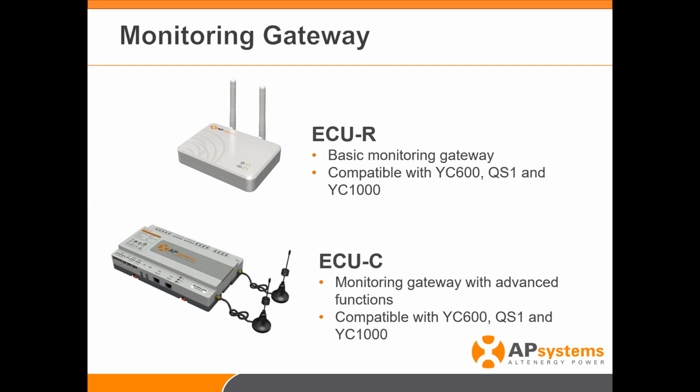It says, what type of commands can I send to the inverters through the ECU, and how can I do it? Very, very simple. So with the ECU app, there's all kinds of commands you can send to the devices. You can send AC parameters to the device. You can do the linking commands. You can actually do serial numbers, scanning of serial numbers, and pushing those down to the ECU. All available through the app.